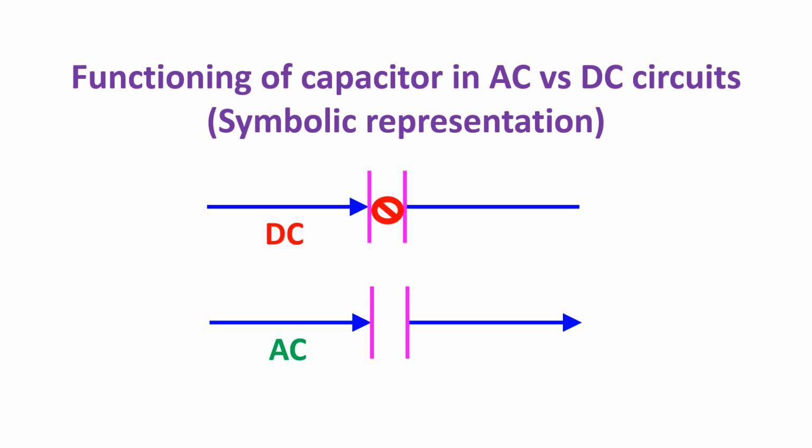usually a fraction of a second, depending on the capacity of the capacitor. Once fully charged, dielectric does not allow further flow of current through the circuit. Initial flow of current is only to charge the capacitor plates and not through the dielectric when the voltage applied is below the breakdown voltage. Beyond the breakdown voltage, the capacitor gets damaged and may produce short circuit.